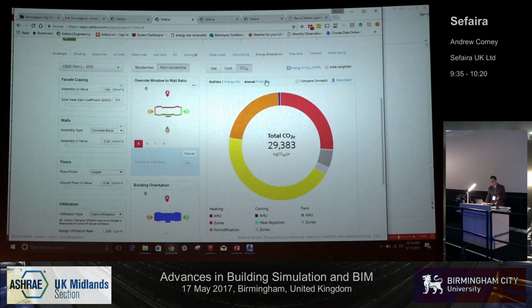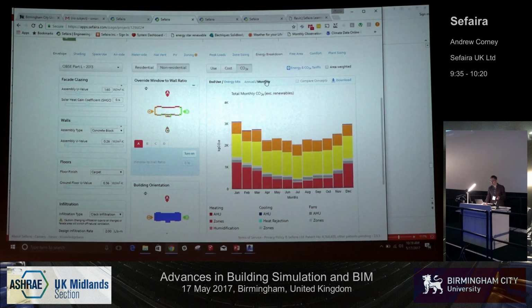And what you'll see that's quite interesting, and this is a result of the way that windows are controlled in natural ventilation systems with heating, is that there's heating occurring even during the summer months. Why is that? Well, when windows open and close, inevitably the heating system is not necessarily going to be fighting the windows, but there'll be extra cooling happening in the building. There'll be cooler air early in the morning and late in the evening. And at the edges of the set point conditions, the heating will still need to operate a bit more than it would for a normal system.